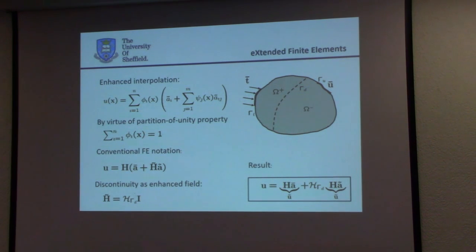Now, when you are doing linear elastic fracture mechanics, you have to do a mix of those. Suppose that your crack has gone to here. Then in the part where the crack has already appeared, you put Heaviside functions as enriched functions. And at the crack tip, you enrich the interpolation with singularity functions. Well, as I said, for cohesive zone models you don't have a singularity, so life is simpler. You only have to enrich the cracked part, the fully cracked part and the partially cracked part, with this Heaviside interpolation.